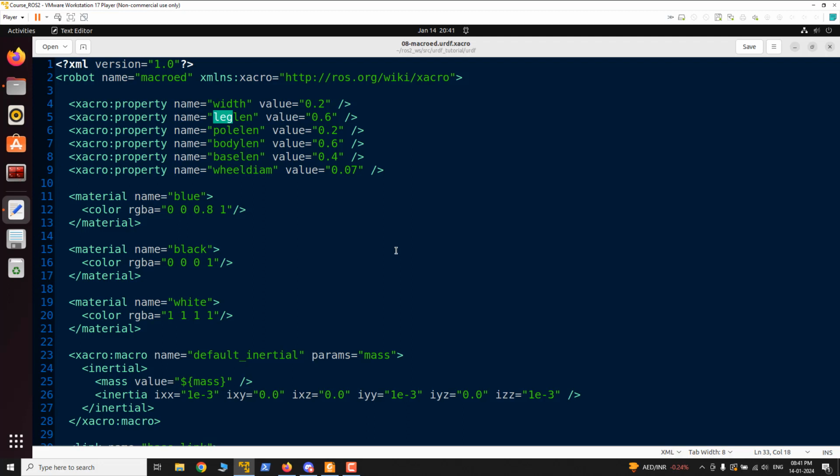But make sure that if you are going to customize it, it will be a pain because there is no programmability or flexibility in the converted URDF. Mostly if you get the URDF, you may need to customize it, because if you have to do the simulation, you have to add the Gazebo plugins. Some tools like Fusion 360 will be adding the basic simulation plugins as well. So if you want to customize it, it will be better, I mean, make sure you have time.